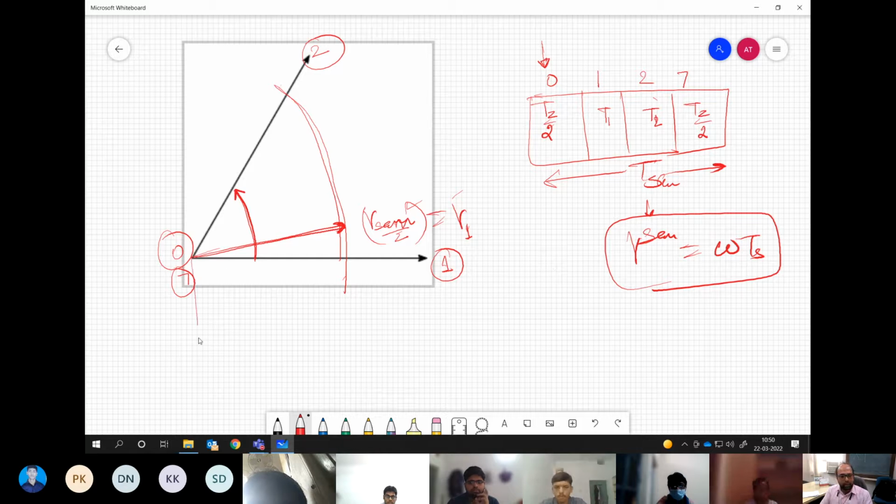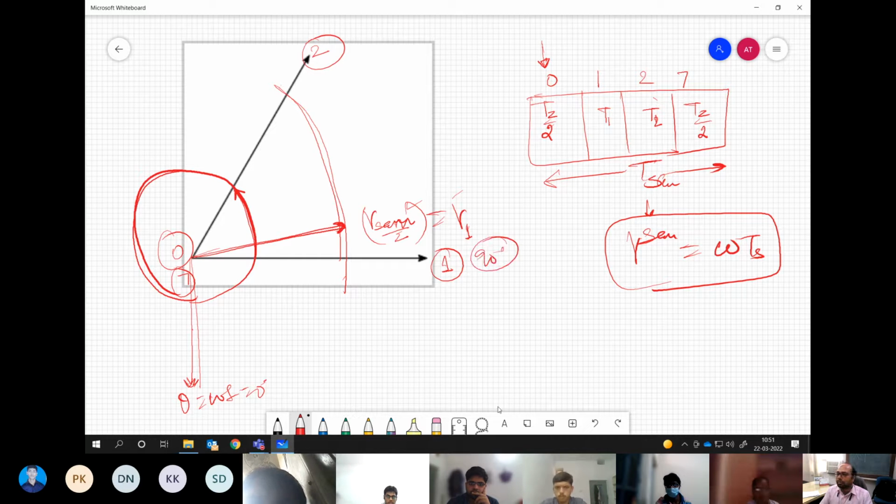Say my theta is rotating. Theta is basically the phase angle, right? Theta equals omega t, and from 0 degrees it starts and rotates continuously, all the way up to 360. There is no problem in that. 90? Okay, why 90? Because we have to match with our peak, or earlier we explained theta is taken from 0. No, that's not the point. We are trying to realize this sample. Say this voltage vector Vs sample we have got over here. What is the meaning of sample?